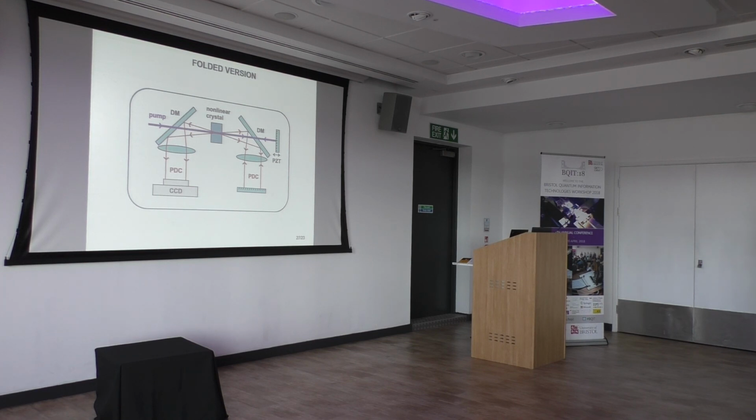And the other point, just a comment, is that if you're doing one of these two beam schemes where you're then recombining them, those beams don't have to be the same frequency. You can sense at one wavelength where you have a very poor detector by measuring at the other wavelength where you have a good detector. That's true.